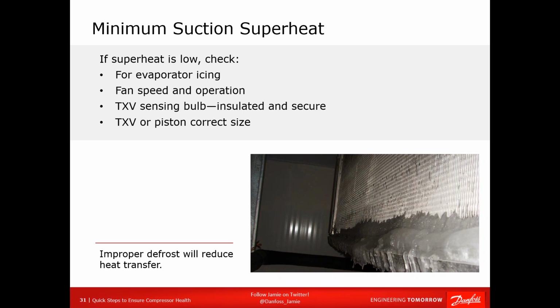Well, evaporator icing. If you live in a place where you have hot and cold seasons, you have 3 times more moisture in the air in the summer than you do in the winter. And this makes a big difference, even in restaurant kitchens, which most people think are pretty steamy anyways. There's still a lot more moisture in the summer than there is in the winter. So if you set your timed defrost up for winter, you are probably only defrosting about half as often as you need to in the summer.